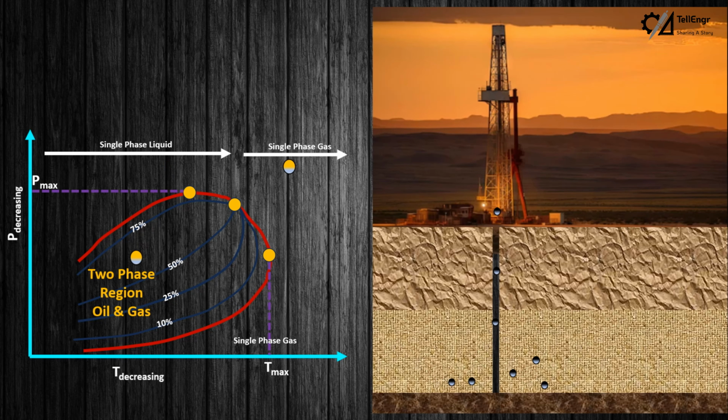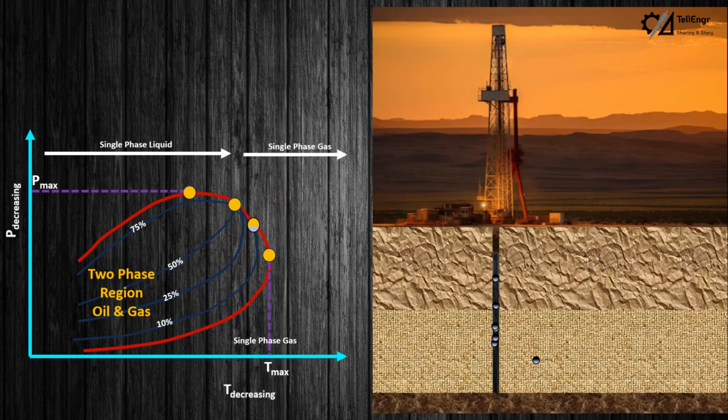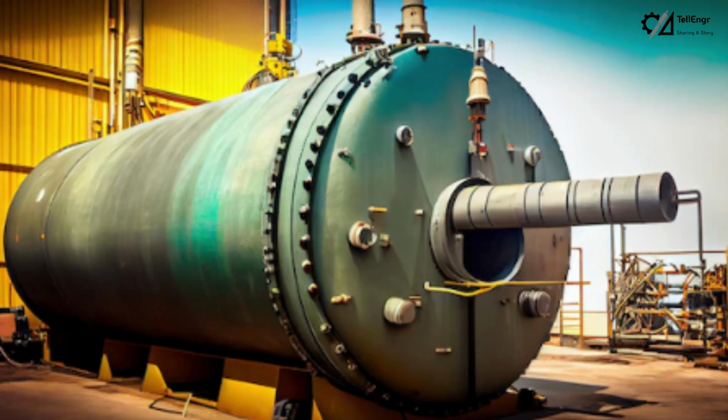Assuming the reservoir initially contains predominantly liquid, the transition to a two-phase mixture occurs as pressure drops. A similar scenario applies to a reservoir with predominantly single-phase gas, where surface conditions can cause phase transitions. To manage this, separators are installed at the wellhead, facilitating segregation of different phases into separate pipelines. However, even with separators, single-phase flow isn't guaranteed through the pipeline, as further changes in temperature and pressure can lead to the reemergence of multiphase behavior.